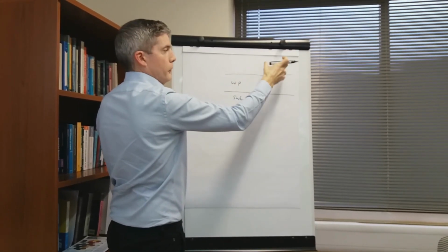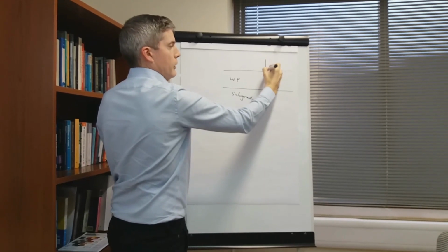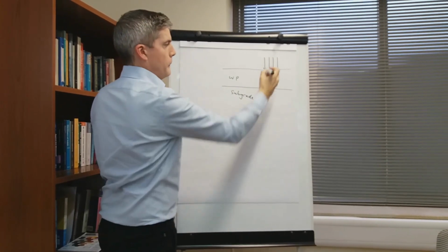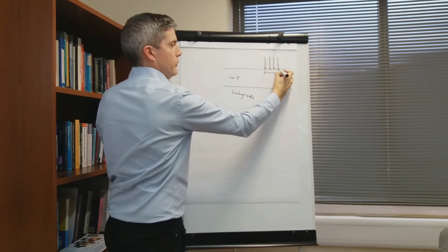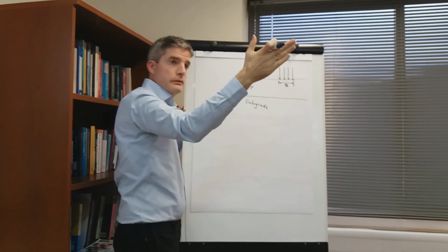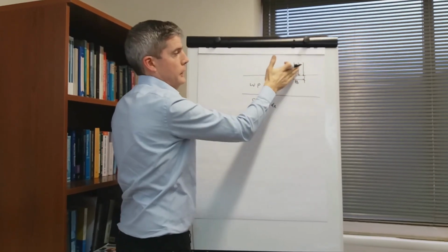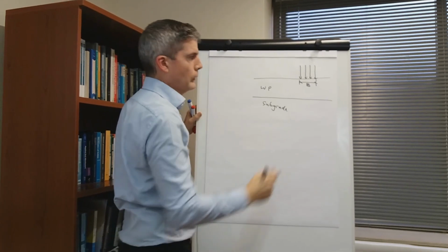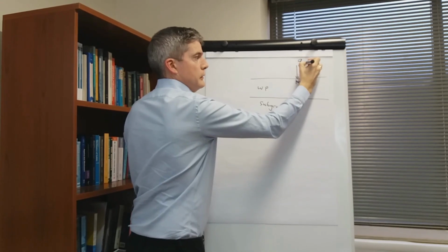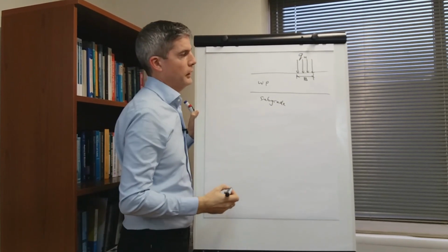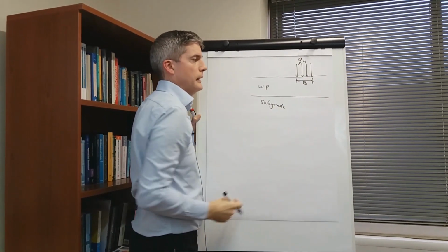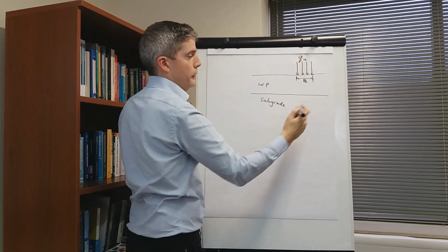A load from a piling rig or a crane, a concentrated load, is applied at the surface that has a width B, and that extends into the flip chart to some length L. What we want to determine is the bearing capacity, or ultimate pressure QU, we can apply to that platform, with a factor of safety applied to have sufficient bearing capacity for that plant.